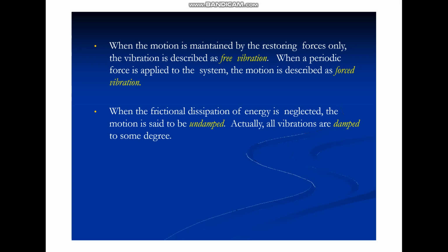When an external periodic force is applied to the system and causes the motion or destabilizes it, this is called forced vibration. When frictional dissipation of energy is neglected, the motion is said to be undamped. Actually, all vibration systems are damped to some extent.